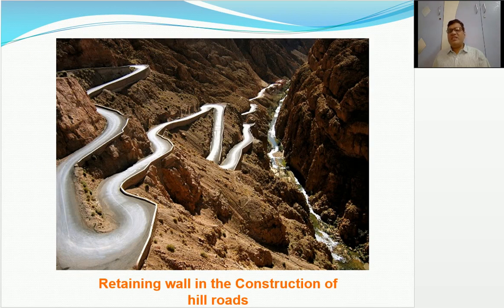Well, let's see some photographs of retaining walls. So here is the photograph of a road in a hilly area. Here on this side you will observe the retaining wall which is provided to support this road pavement. Many times you will find retaining walls are also provided on the other side to prevent landsliding. In this case such walls are not provided, but in many ghat sections you will observe retaining walls on both sides of the road, that means below the pavement level on the outer side and above the road level on the inner side.